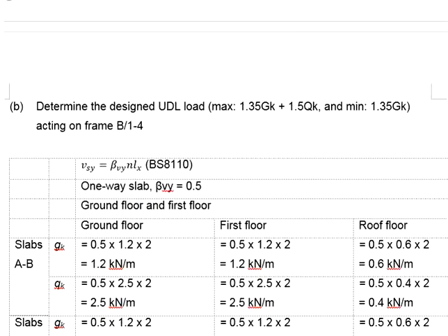What does it mean by the maximum load? We are talking about the ultimate limit states, where both GK and QKs are present. Ultimate limit state will require the factor of safety for the GK and QK, 1.35 and 1.5 respectively. As for the minimum load, only GK is present, but the QK is not present. Also, we deal with the ultimate limit state. Therefore, you're going to need this factor of safety of 1.35 for the GK.